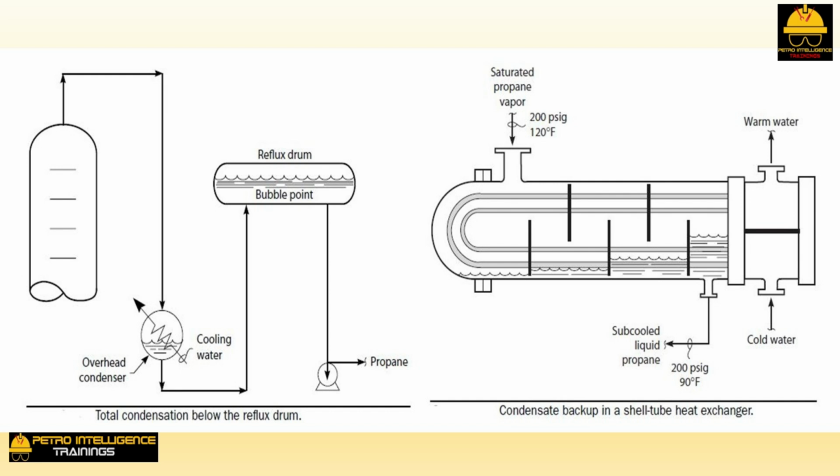Heat removed by condensation is easy. The heat transfer coefficient U for condensation of pure, clean vapors may be 400 to 1000 BTU per hour per square foot of heat exchanger surface area, per degree F of temperature driving force. The U value for subcooling stagnant liquid may be only 10 to 30. Condensate backup is the major cause of lost heat transfer for heat exchangers in condensing service.